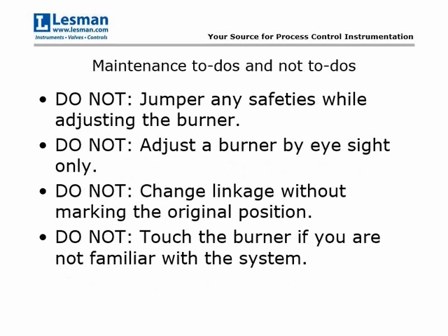So you want to have that set to a certain position, and then if you're getting to the point where you need more fuel, at that point you can go into your pressure switch and just increase that setting as opposed to jumpering that out until you need it. You definitely want to not jumper any safeties and keep those all intact.